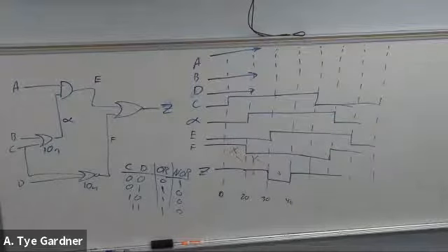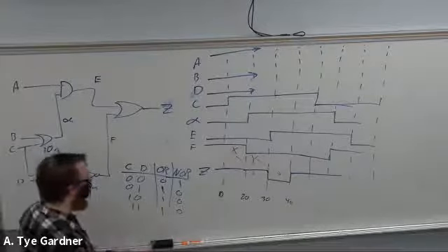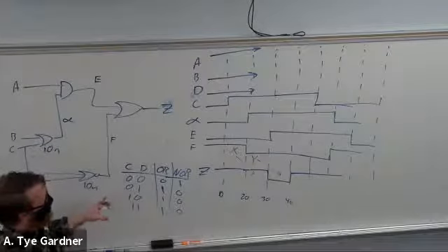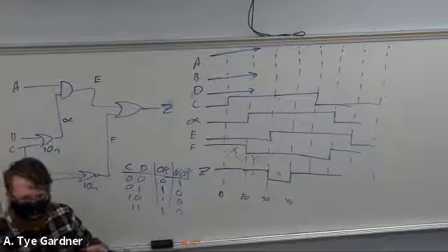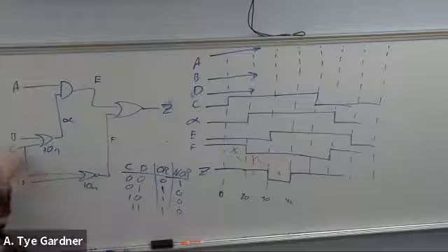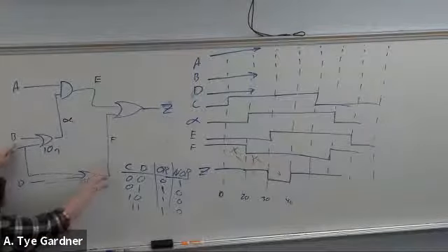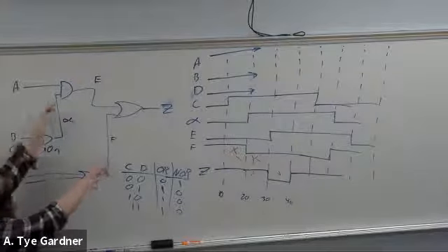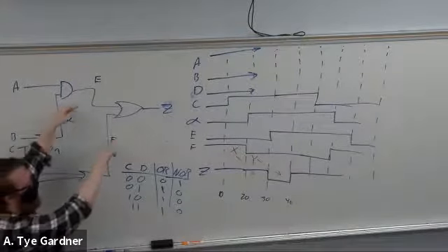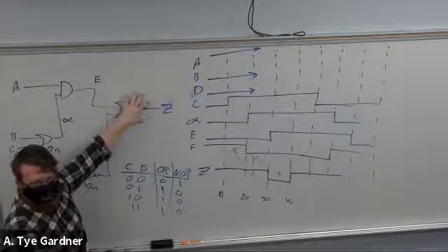Would toggling C faster just make the glitch harder to see, or would that create more? It makes it difficult to see. The issue is that you're still going to have the hazard, but the delay path can do really weird things because it takes longer. This one could still be correct while this one is wrong, and so it ends up overlapping and disguising the hazard.